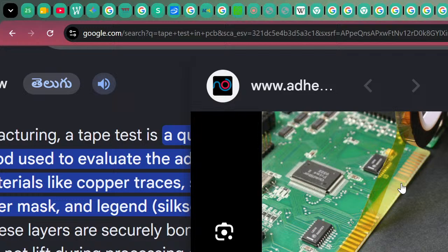With a little bit of force. So if gold is sticking with the tape, then it means the adhesive forces between the gold and the nickel are not very strong. That means it is failing the quality control. Okay, the piece is treated as QC failed.